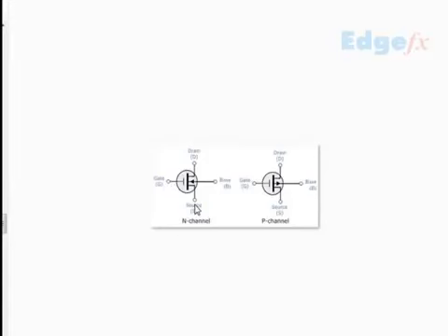If it shows low resistance, it is okay. In the reverse, it should show very high resistance. But if in both cases it shows the same value, or a very low value, then it is shorted. That means gate to source is shorted, and it has gone bad or defective.